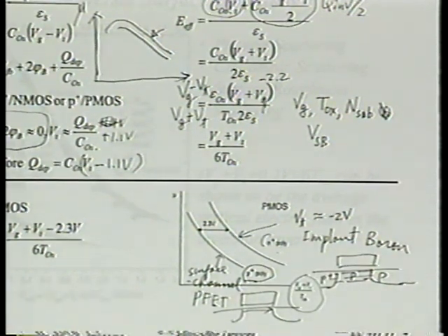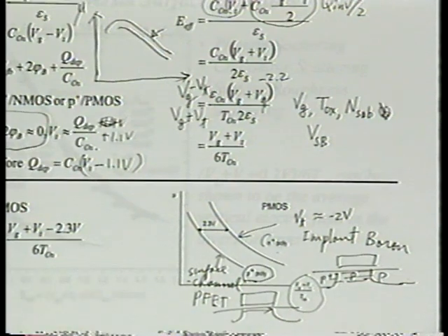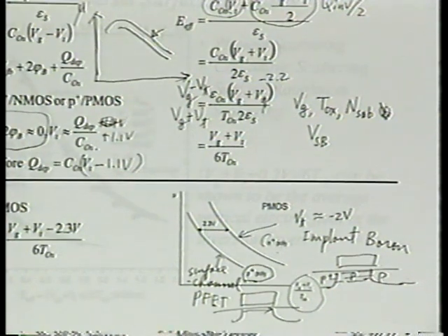Now, for those of you that have been working with companies, you know it's standard terminology, buried channel transistor. But I bet if you do a 2D simulation under at least strong inversion, and certainly this is strong inversion, that's where the mobility is measured, guess where the current is flowing? Definitely it's at the surface, all right?